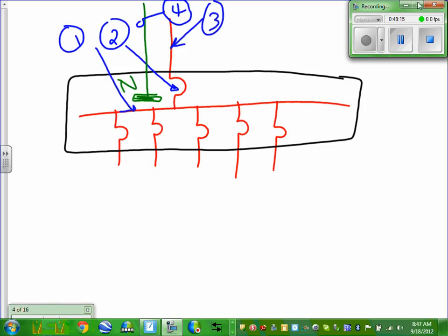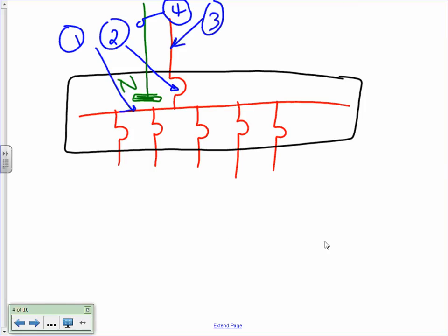Go ahead and start, as I said. If you guys want to draw a little bit of a sketch like this, this is what we're trying to achieve. The whole load calculation, Darren, is to come up with a panel size, an overcurrent protection device inside the panel, which is typically the same size, the conductors coming to the panel, and the neutral, because we have to derate the neutral. That's your main panel. That's going to feed all these loads inside it. Okay? All right, so if you guys want to draw that one.